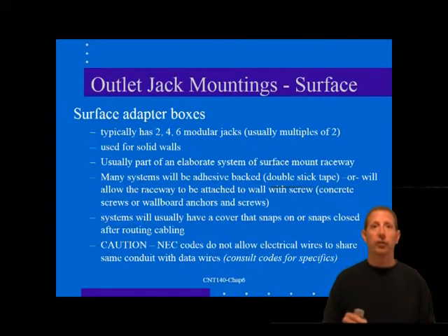Please be careful when using these self-adhesive raceways, because once they're stuck on, they are there to stay. And if you don't have them on perfectly straight, you're going to be staring at that crooked raceway until eternity. The boxes may also come with foam mountings, but you are better advised to secure them to the wall with screws. The screws also help stabilize the entire raceway system.